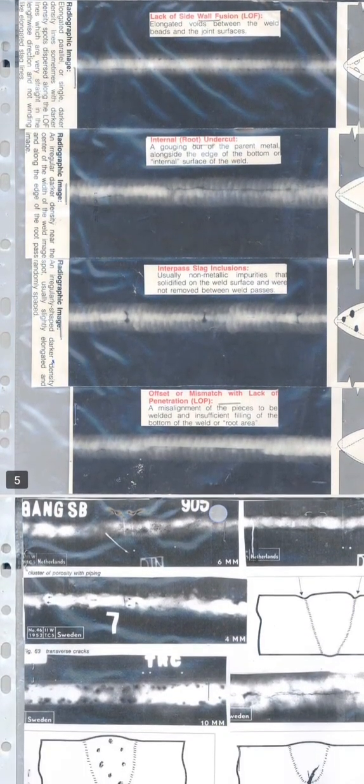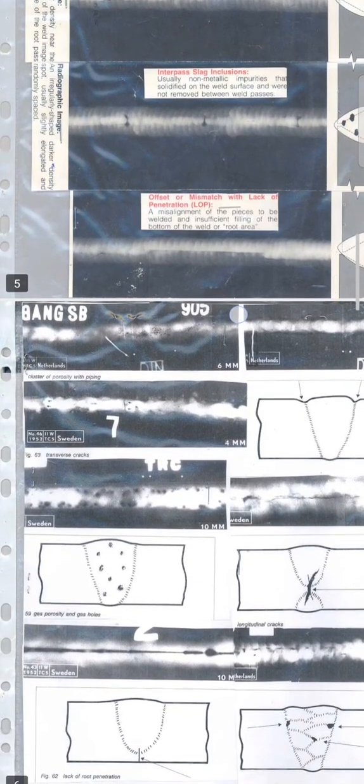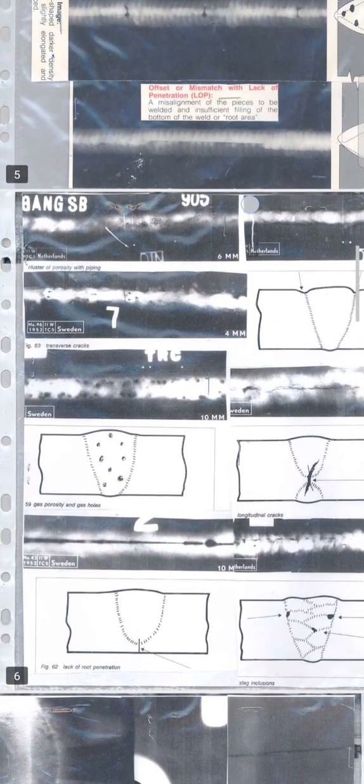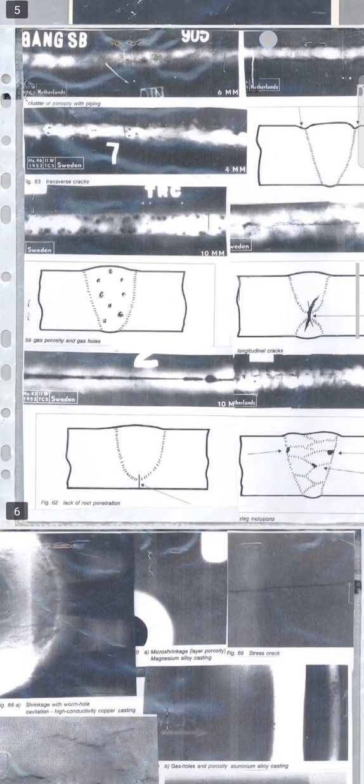Slag inclusions are non-metallic solid material entrapped in weld metal or between weld and base metal. In a radiograph, dark, jagged asymmetrical shapes within the weld or along the weld joint areas are indicative of slag inclusions. Cracks are thin, straight or jagged, linearly disposed discontinuities that occur after the melt has solidified. They generally appear singly and originate at casting surfaces.